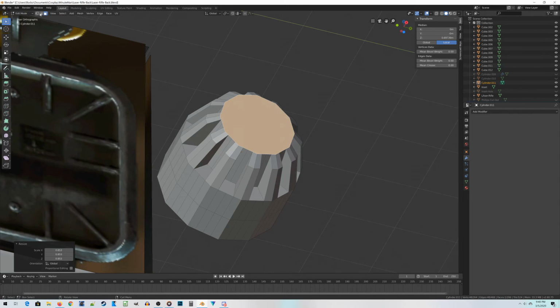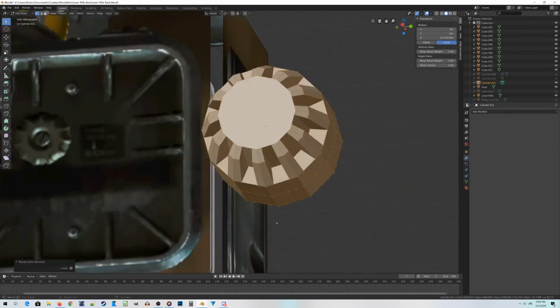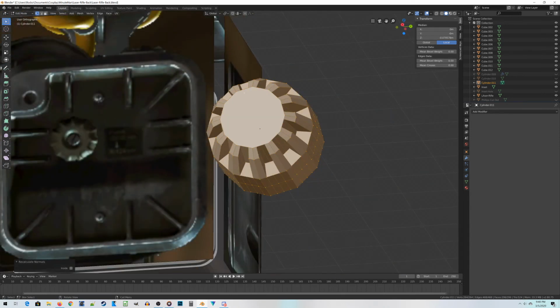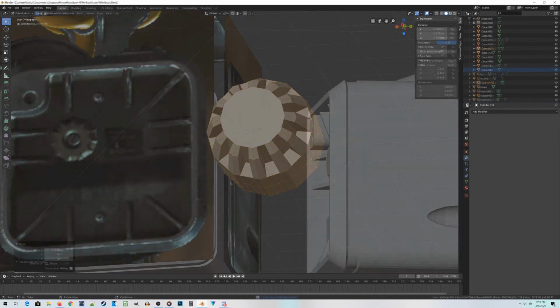And then I want to switch over to vertex mode, select everything, and do Shift N for just 3D math stuff. Just don't worry about it, just always hit Shift N. It will fix problems. And then let's move this piece into place, and we're going to do one sort of Boolean operation to create the little groove for the bolt.